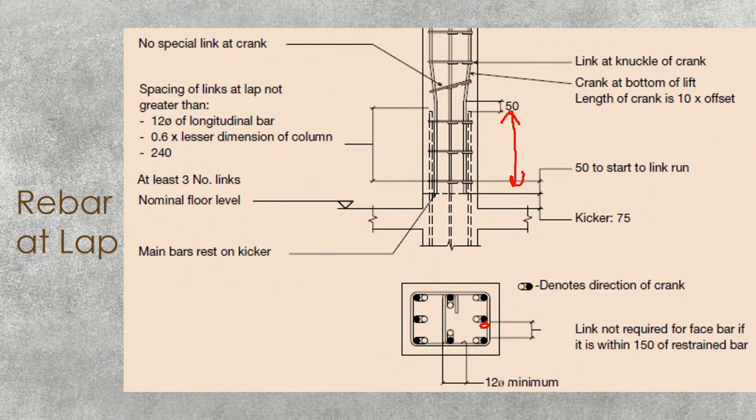So in the design also, you have to do the design and the detailing of the reinforcement accordingly. With that, you reduce the complication, and the strength of the joint also increases, because when you have cyclic loading caused by an earthquake or any other similar kind of load, failure is caused to the joint. If you have detailed the joint correctly, then just above the joint the bending will be higher, so this area would fail easily if you have a weak joint here.